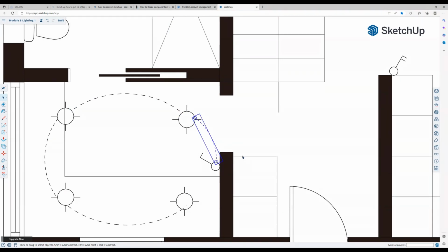Explode. Maybe I can make this a bit bigger just so that the dotted lines look a bit more similar. Okay, so that's lined up. Now I'm going to explode it. And then right click, explode. All right. So delete the circle.